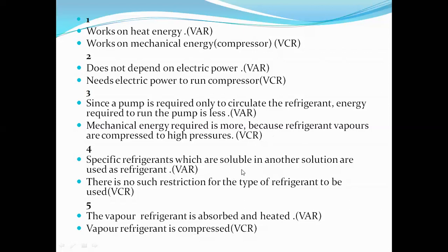Fourth one is, we use only particular refrigerants in case of VAR because we use a refrigerant and absorbent, like ammonia and water, or water and lithium bromide. Such a condition is not applicable for VCR. We can use any type of refrigerant in case of VCR.